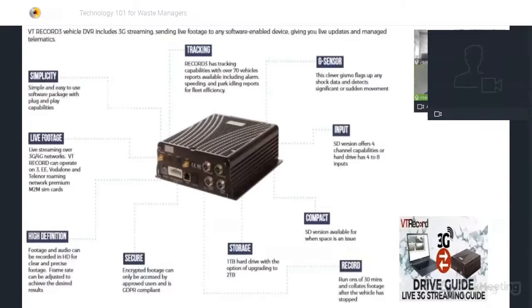Predominantly, there is a standard specification that certainly Vision Techniques would offer, and that would normally be on a standard refuse truck, a 4-camera DVR system covering the front, near side, offside and rear of the vehicle, an onboard recording system that would give the authority between 30 and 60 days of stored recorded footage on board the vehicle. And then the added ability to access that recorded footage live at any point during a 24-hour period through a remote connection, whether that's 3G, 4G, through your mobile phone or your tablet.